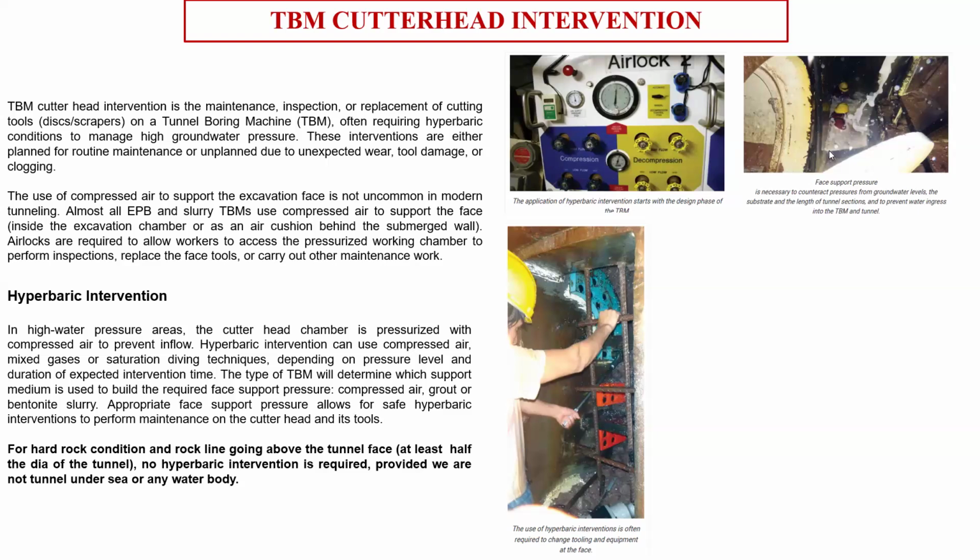So because our main purpose is the segment should be a watertight structure. So 100 years if I consider, it should be watertight as well as a durable structure. So if the segments have gone out of tolerance, then the designer instructs the contractor to submit a method statement on the rectification of the segment.